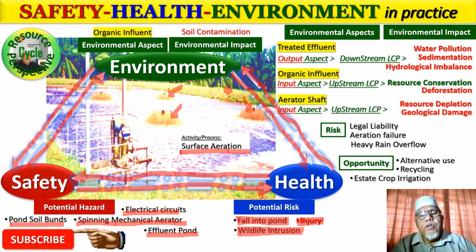Now, what comes into this pond is a partially treated biological organic effluent, high in organic content because it comes from the palm oil mill effluent, and the BOD is easily in the region of say 400 to about 800 milligram per liter, COD maybe 1,000, after passing through the first few ponds before this.